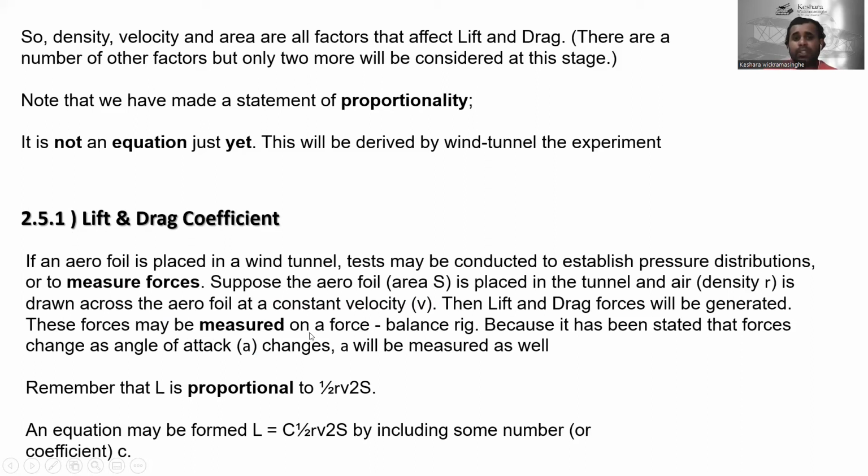These forces may be measured on a force balancing rig, because it has been stated that forces change as angle of attack changes, which will be measured as well. So remember that lift is proportional to these quantities, right? So an equation may be formed: L equals C times half density times V squared times S, by including some number or coefficient. Here C is the coefficient of lift. All right.